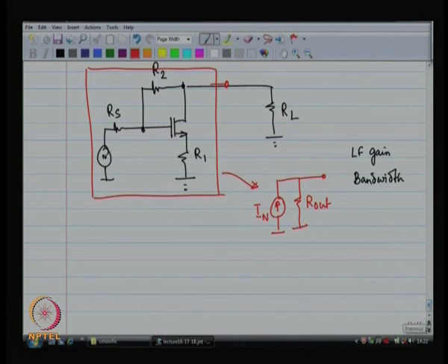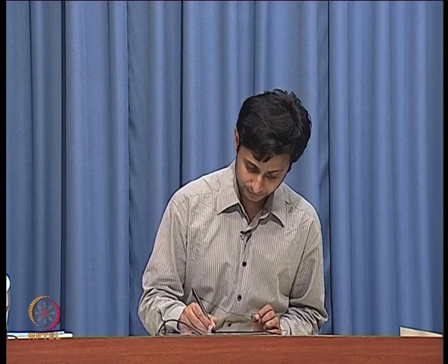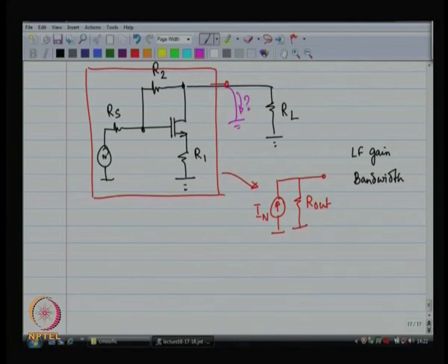So, to find the gain, to find the Norton equivalent current, what experiment do we do? We do the short circuit experiment. We short the output to ground and see how much current is flowing here. That will tell me what is the value of IN. If you do it here, then IN will go through the short circuit. So, that is why short circuit experiment, right, just a reminder. So, we are going to do the short circuit experiment.